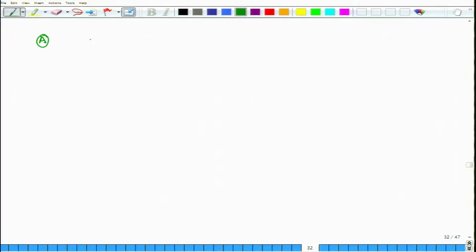So, case A, theta is equal to 45 degrees, and with that sigma L is equal to tau xy, right, because it is tau xy cosine square theta. Okay. And sigma T is equal to minus tau xy, and tau LT is 0.